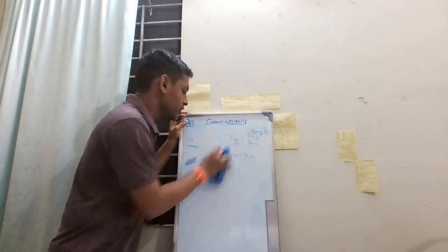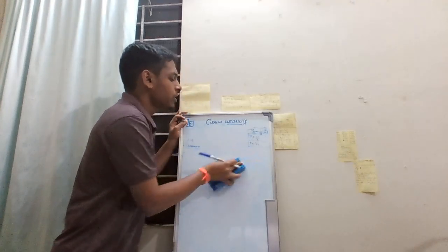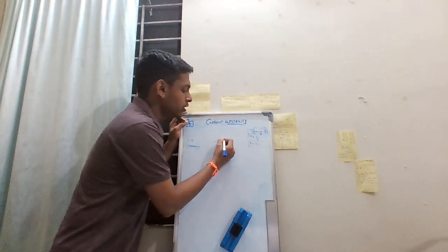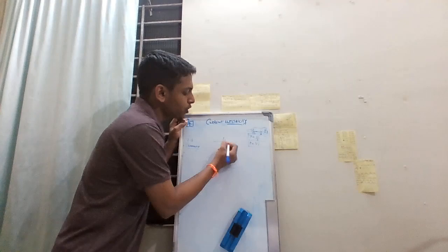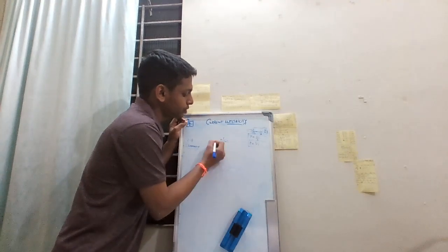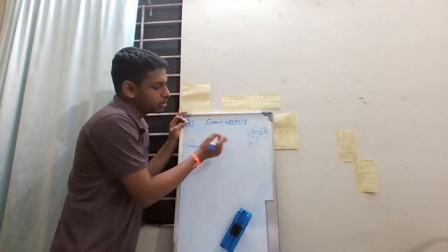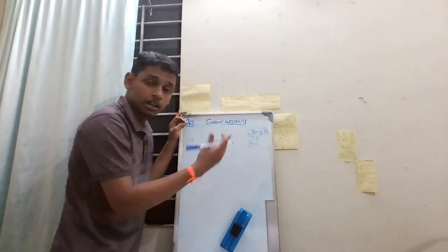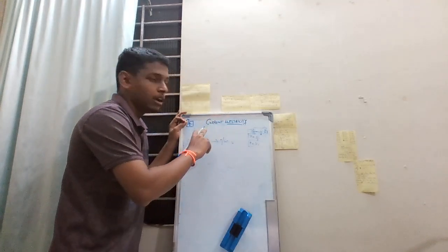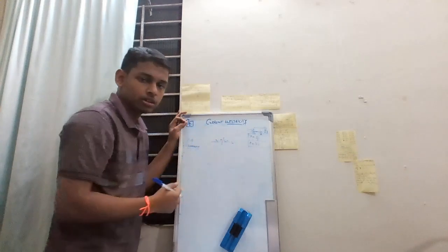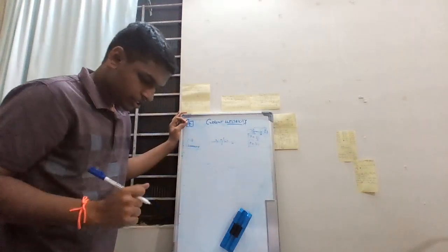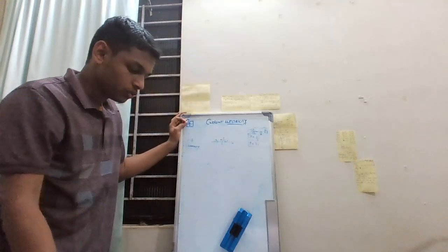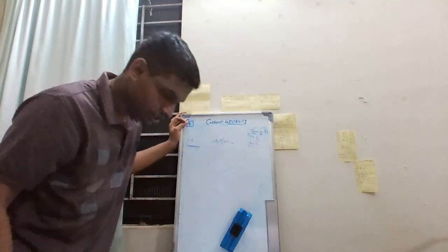So this is source. But what if it is load? When it is a load, then it will move from higher potential to lower potential. Current is approaching the positive terminal and moving out of the negative terminal. In that case, it will consume the electrical power. Next, we have some examples where we find out which is load and which is source.